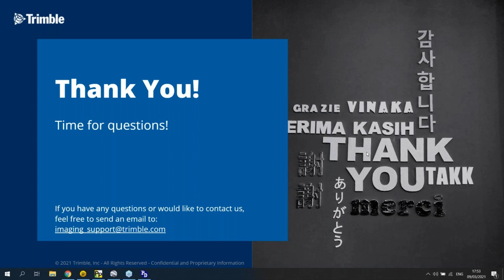No, unfortunately not. The processing engine behind the data that comes from mobile mapping systems is different from the processing engine in TBC. You process your trajectory in POSPac, and this is different than processing your raw data, or GNSS measurements, that come from the R12 in TBC. So the engines are different and the behaviors are different. At the end of the day, the R12 utilizes multiple sensors, like the tilt sensor, to reach a good solution in difficult conditions.